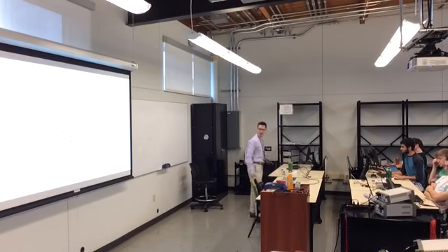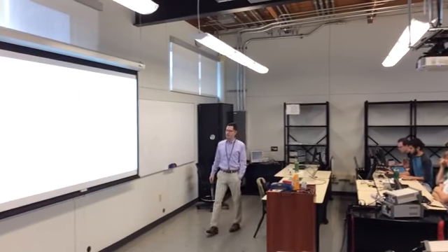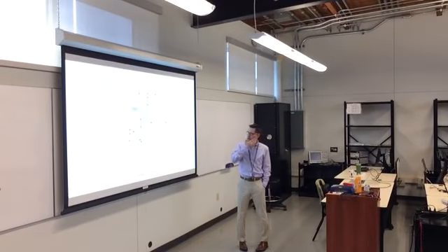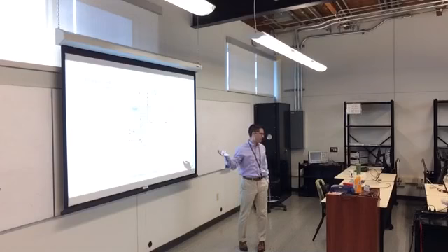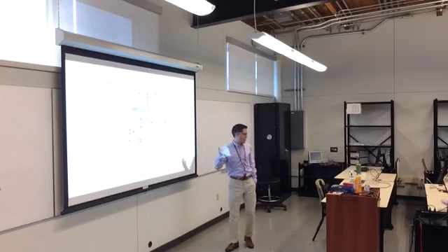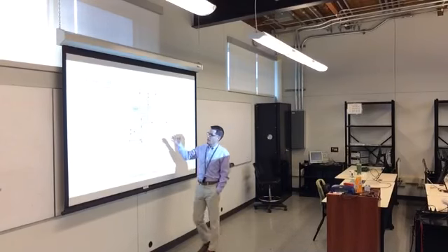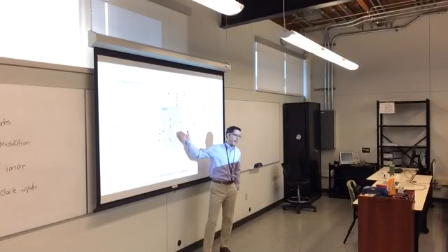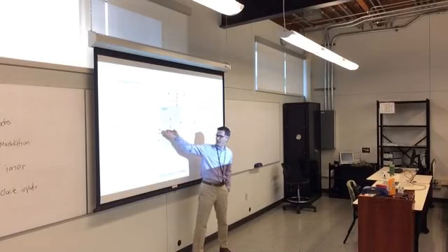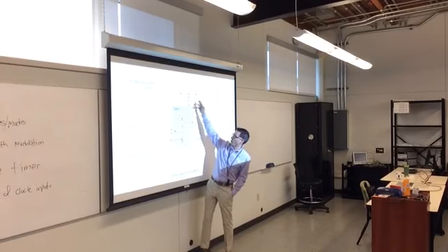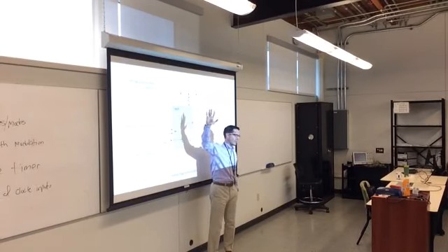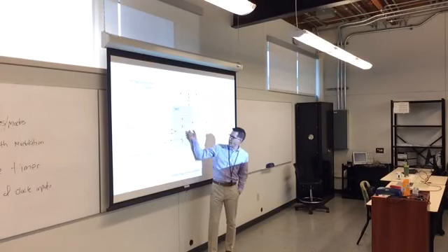If you take a look in the application note, there's a general functional diagram of how the timer operates. This isn't everything, but here's the basic idea. In the middle, you've got some counter, and it's going up or down. That counter is driven by some sort of clock. The clock can come from the processor, the peripheral bus, or from other devices. It comes from a variety of places. The counter can also look at some sort of input signal.